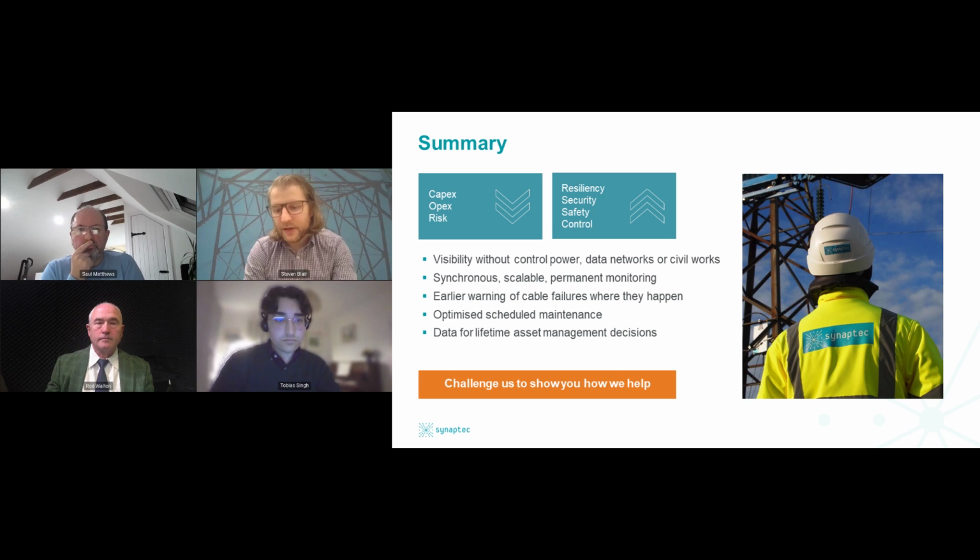So right now that's an offline capability that we have, and something we will build into our real-time online pipeline of data processing in the near future. And that will capture a few capabilities, such as real-time thermal rating of these assets, particularly taking into account the detail that you get from the sheath current measurements, because that can give you a lot of information that you don't necessarily get from conventional ways of doing this. So the answer is yes, and we're working on that type of system to deliver that in the near future.